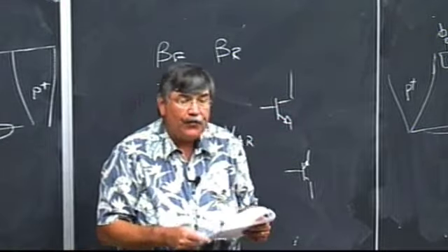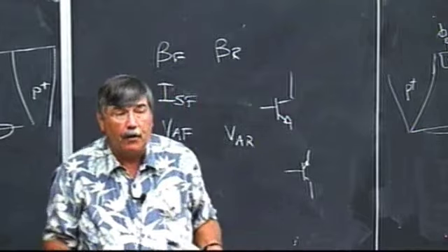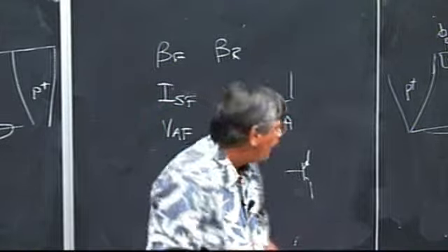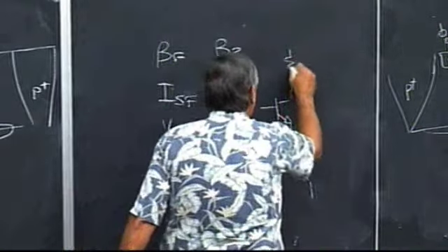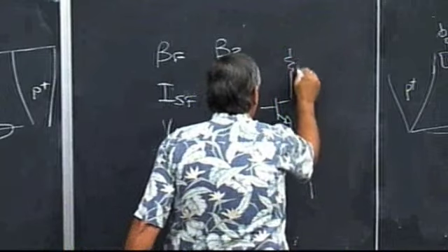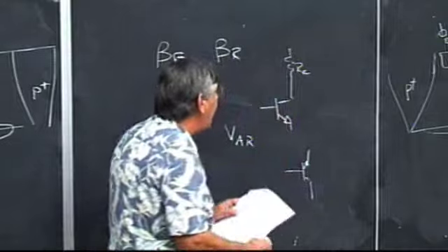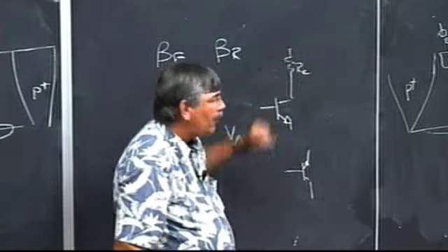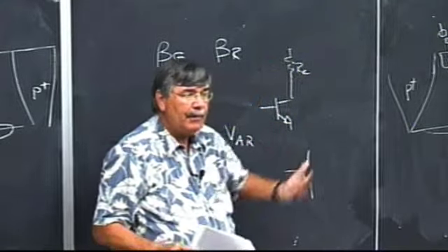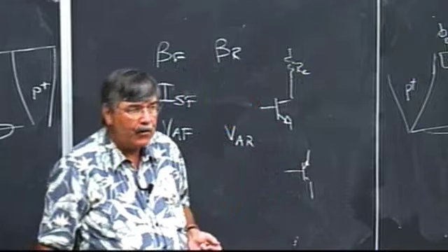There's a resistor in series with the collector. It's called RC. You take the transistor model and you just add, internal to the model, this extra resistor, RC. Now notice that if the doping is very light or if the path is very long, then this RC will be fairly large. Typical value might be 100 ohms or so.